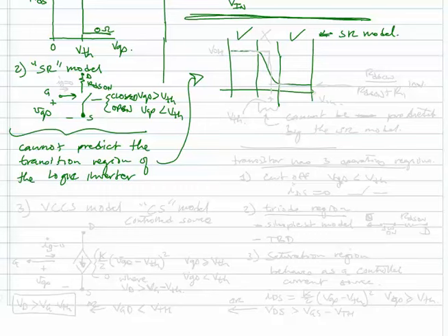It can tell you if, for instance, Vn is greater than some amount, eventually here, this voltage, we looked at this in class, is simply going to be the RDS on over RDS on plus R1 times 10 volts. Okay, you can just use the SR model for that.